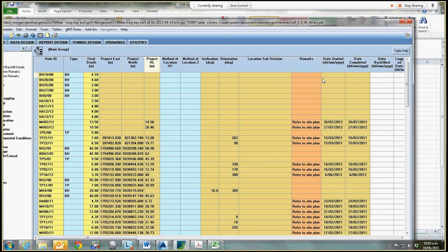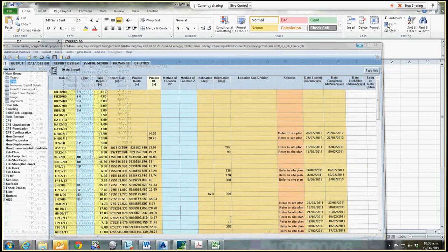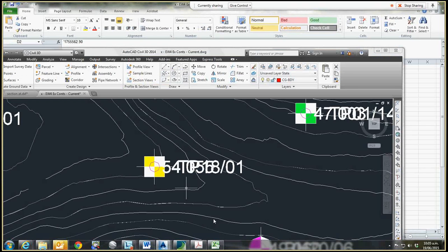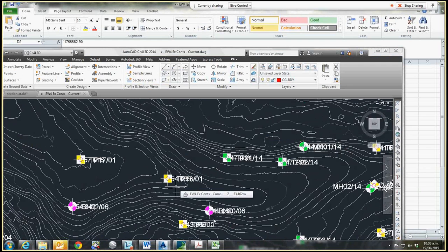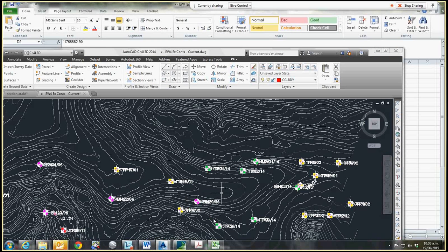Well, sweet. That's another method I learned today. Yeah, because what I used to do is I used to assign them as Civil 3D points, and you can project Civil 3D points to follow the surface. And then just output it, because you know how you mentioned in this session before that you can't do the projection as in correct offset around the cross section and the long section for the boreholes.